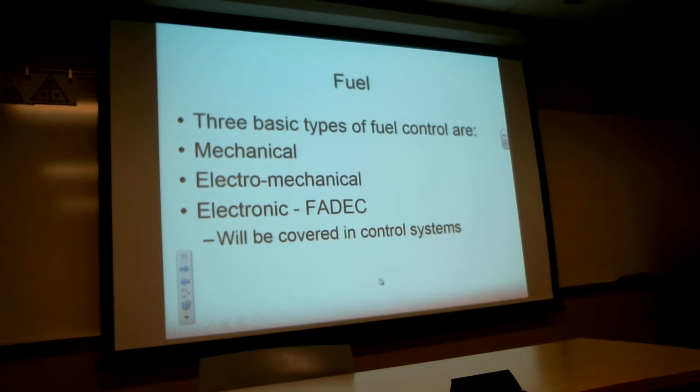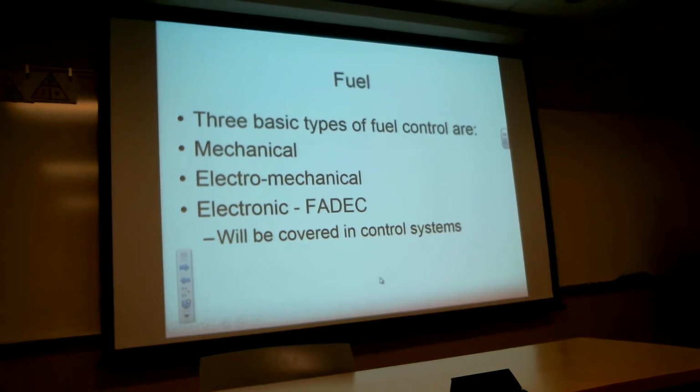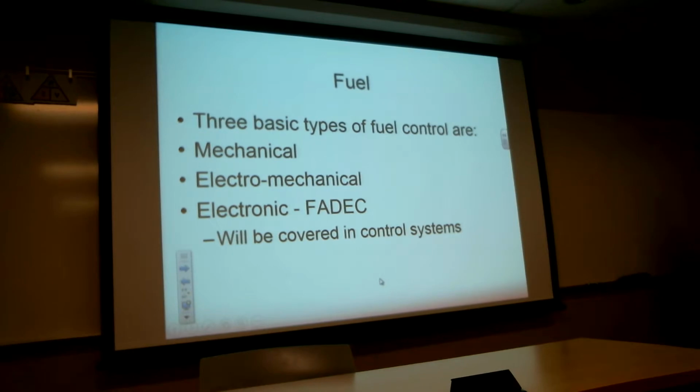Okay, so you've got three basic kinds of fuel controls. I'm just going to touch lightly on the FADEC, and even lighter on the other types. First, the mechanical fuel controls. This is all cable controlled or push rod controlled. It's directly mechanically attached to a throttle. It could be a helicopter or a fixed wing aircraft, it doesn't matter so much. Most of the old mechanics call them carburetors because they operate pretty much like carburetors. In fact, all three of these work a lot like governors on propeller systems. They use flyweights to very accurately measure the RPM they're being fed.